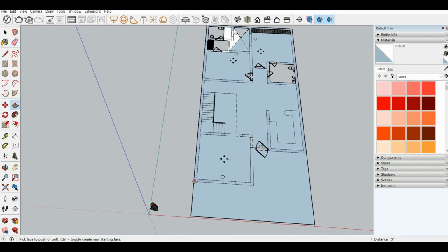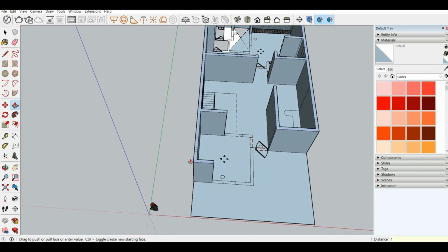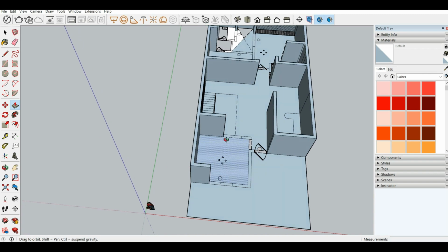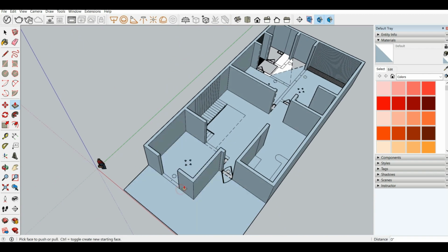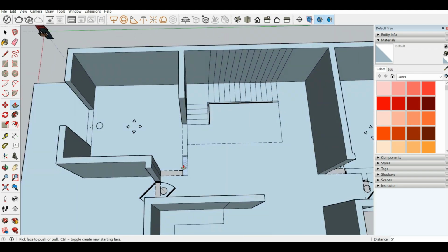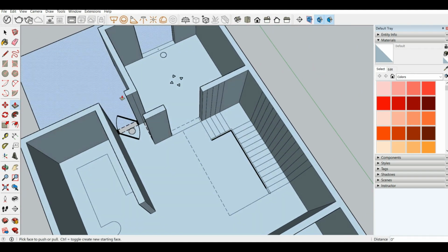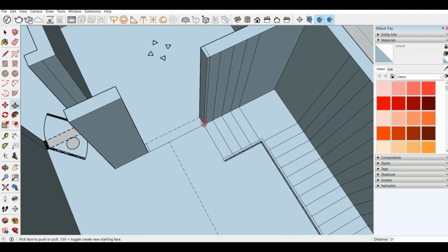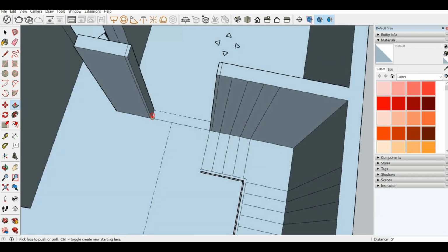This will help us to directly lift the walls using the push-pull tool. So we want the height of near about 10 feet. So I will type in the dimensions box. Now we'll have to check if there are any walls that are left and lift them manually. So I'm including all of the geometry which was left by SketchUp.